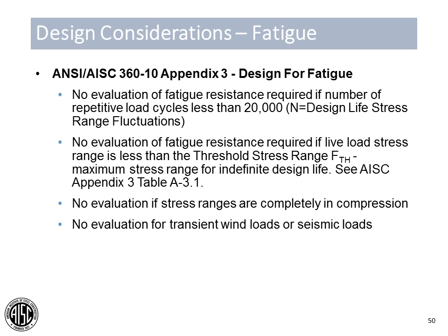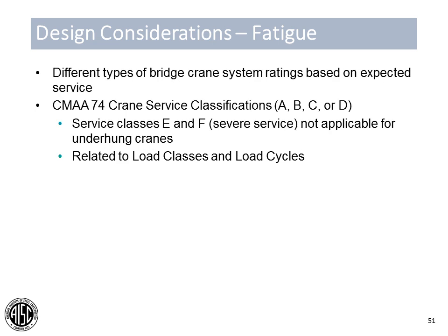So if your design stress range is above this threshold stress range, then you need to consider fatigue in your analysis. If a component or an area of a component is completely in compression, you do not need to consider fatigue in that instance. And also, transient wind and seismic loads do not need to be considered for fatigue design.